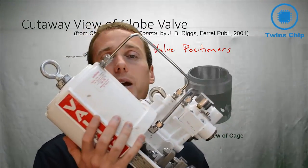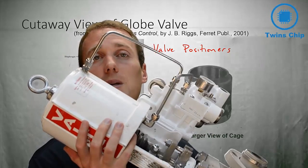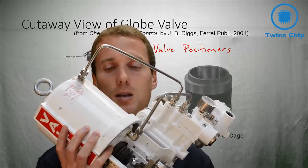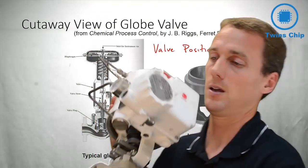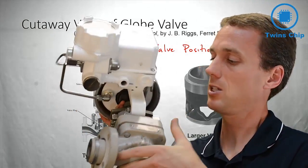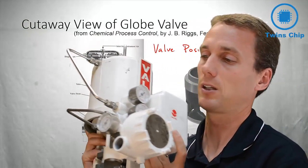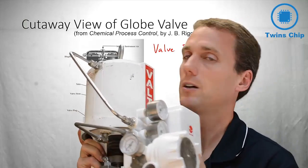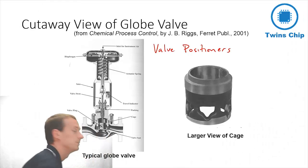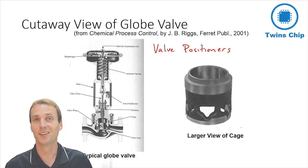So instead of being actuated by or moving by a spring, you actually have air coming in from the top and the bottom. And so this is one example of a valve. And you can see the cage is going to be down here, and this is the part of the valve positioner right here, the controls that go into that. Okay, so I'm just going to go ahead and set this down. Okay, so that is a globe valve, for example.